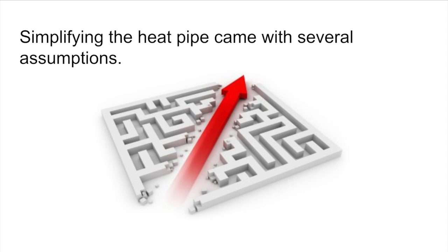The first assumption is that there was no radial heat transfer. This allowed for the heat to enter one end and leave the other end of the pipe. By doing this, it was only needed to take the temperatures at either end of the pipe. Another was that the pipe had uniform thickness when in fact there were joints where the thickness doubled. The assumption was also made that there was only air or only water vapor and never a mixture of the two. Because it was a sealed pipe, temperature measurements and pressures had to be estimated.